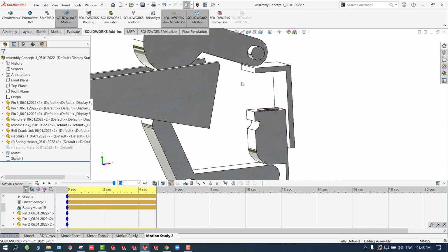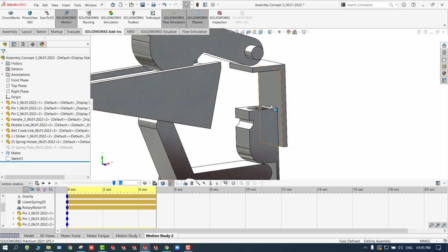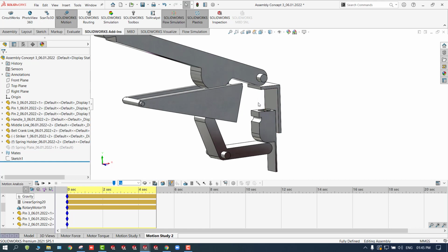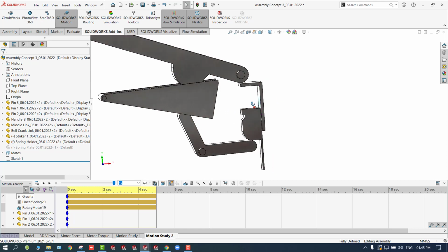So practically it is not, because if I add a wall here, if I define the same mechanism, if this particular face touches this wall which is added here, it will automatically cross that wall, because practically it should stop. But here the software just takes the input you're giving with respect to the analysis, and according to that it will produce a mechanism. Okay, it won't take these particular contacts into account.